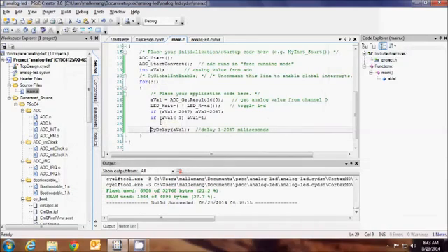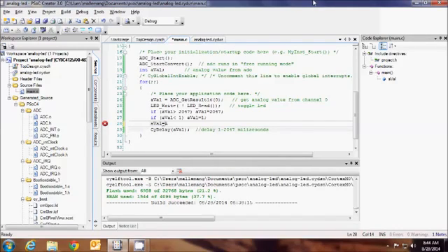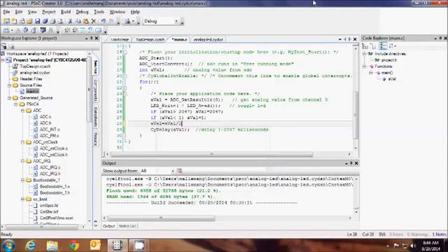Arduino gives you the map function, I think it's called. But anyway, I'll do a little y equals mx plus b, and I will just take the analog value, divide it by 2. I don't need to go all the way to 2000. This will take me to 1000. And then add a 100 millisecond lower limit. So divide by 2 and add 100. And that'll give me a better range for my analog.